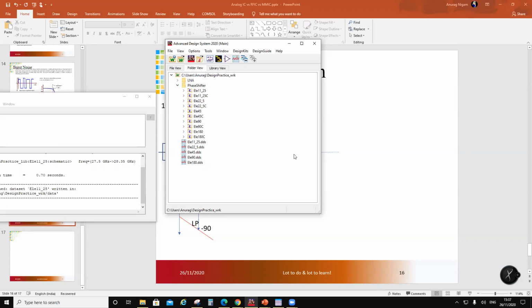So I don't think there will be an application where you will need to go 6-bit or 7-bit or 8-bit. Even if you have to go, don't implement them as a high pass, low pass, band pass element. Rather, just take two lines and let them differ by 5.625, or let's say again 2.8, whatever is half of it. So don't use beyond this. Don't use these equivalent elements. Just use the length of the lines differing by an angle, and you will accumulate certain phase error across the bandwidth. That would be tolerable.